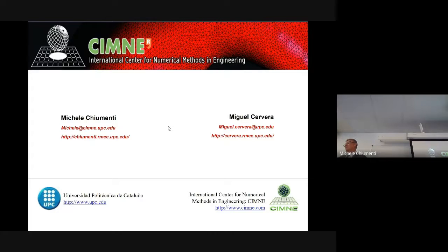Okay, I can imagine that the softening part would be different because of the energy release, because we have a larger volume, and the crack surface is scaled quadratically, and this is scaled cubically. So this is the difference. But I just wonder about the peak load, I mean, about the nominal strength. If there are no notches, if there is no stress concentration, I would just assume that the stress is increasing homogeneously until we reach the strength.